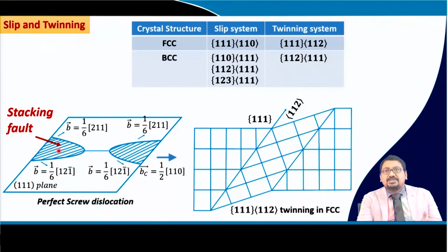So, plastic deformation of any material does not only need the glide on the slip plane, it also requires cross slipping in order to activate multiple planes and multiple directions, so that a homogeneous deformation takes place, along with which the climb of edge dislocation suffices for a proper homogeneous deformation of the material.